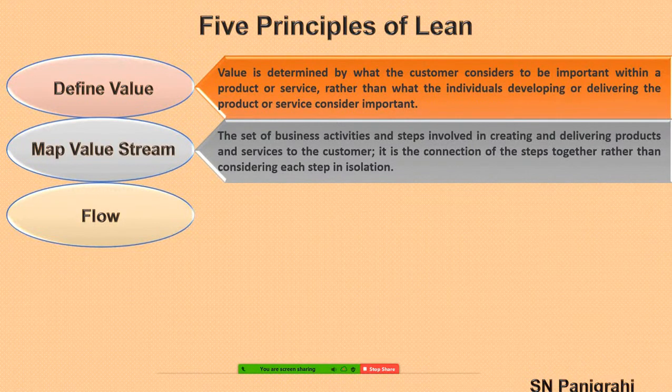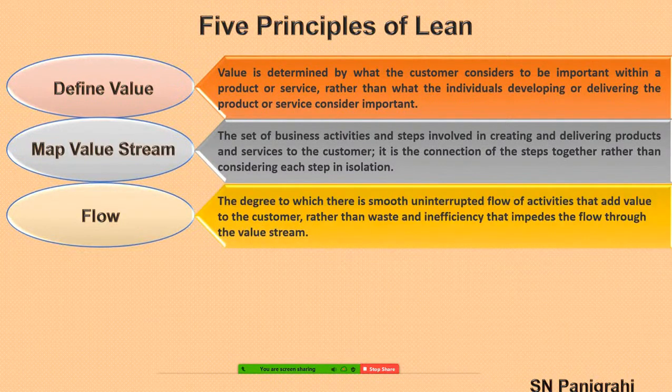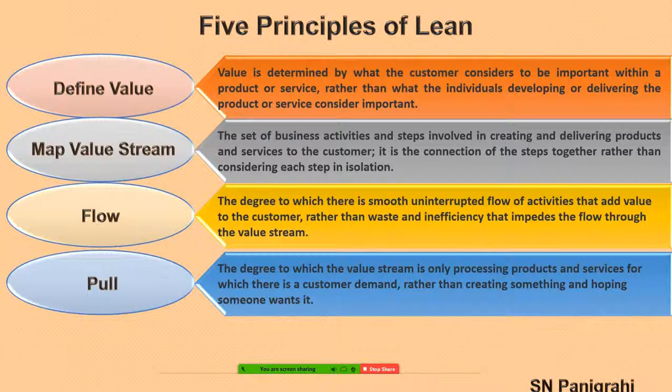And then it is value stream mapping. So we have to make 2 mappings. One is the current process, what the process flow is at present, and then after the improvements, of course, we have to make the final mapping. That is called value stream mapping. Then we have to see how the flow is, whether any extra flows or wastes are involved in that. We have to eliminate them so that we minimize the route, and eliminate the unnecessary steps in the flow.